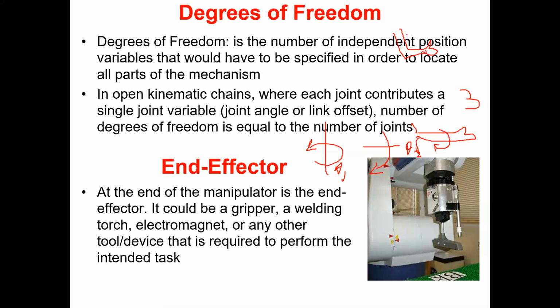So this angle is one joint, theta 4. But there is another joint. If you look at this axis here, you can actually twist it like that. The forearm you can rotate around the axis of the arm itself. So this is theta 5.